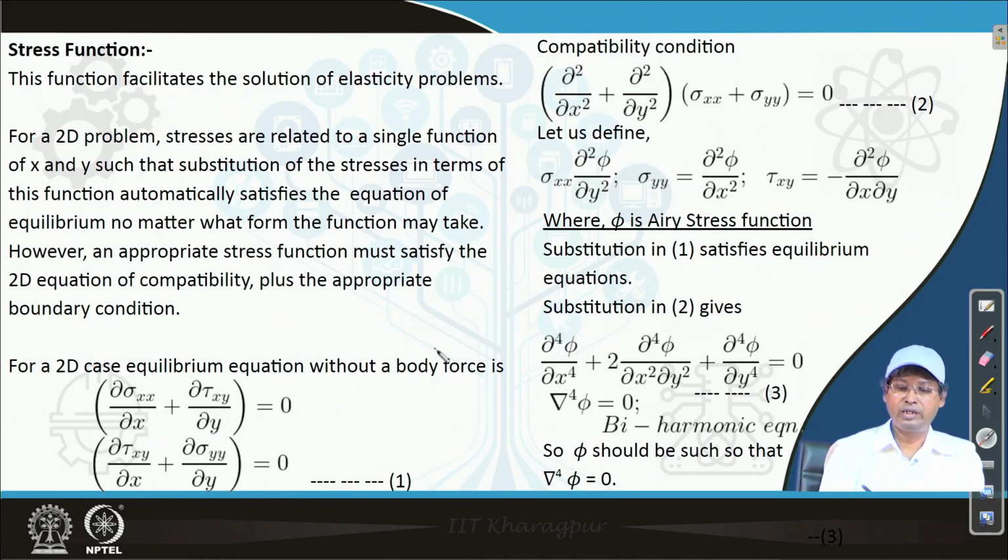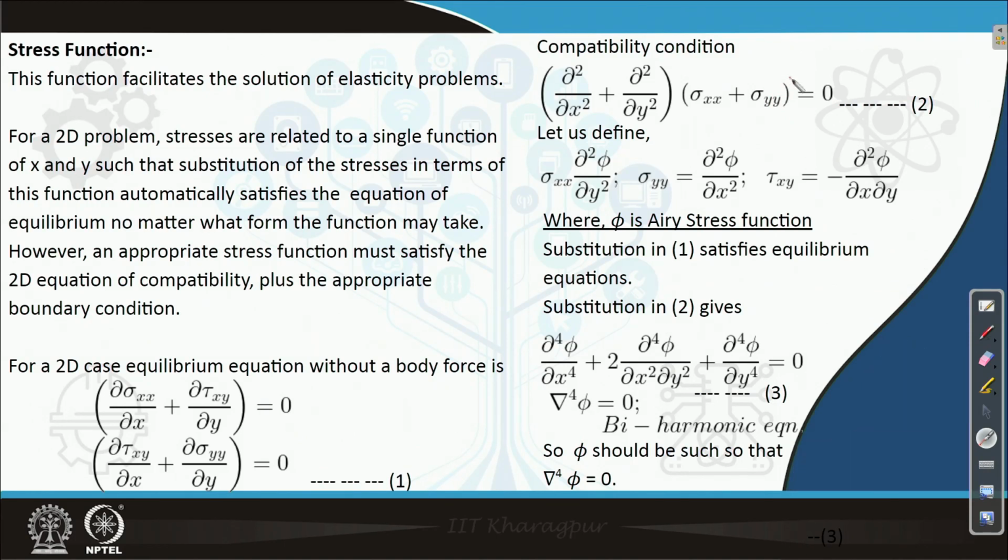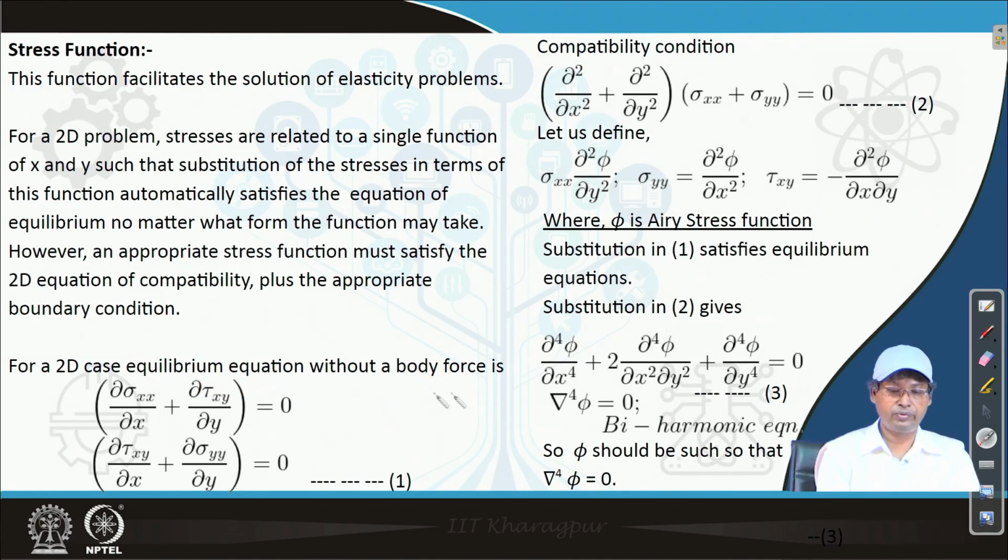So, this has to be done. Instead of the surface forces capital X and capital Y, the compatibility equation in terms of stress reduces to this one. We also have, for a 2D case, the equilibrium equations without a body force, when we do not have any force like that.